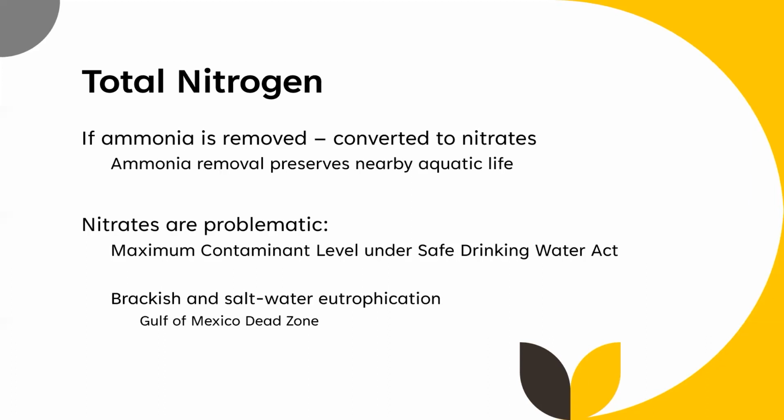First, especially in Kansas, where we have a lot of systems with limited water supply options for drinking water supply, the Safe Drinking Water Act has a maximum contaminant level for nitrates. If you're upstream of a drinking water intake, making sure you control nitrates is helpful to your neighboring communities. It's especially so during times of low flow, where your discharge from your wastewater treatment plant ends up being a large portion of the receiving water body flow.